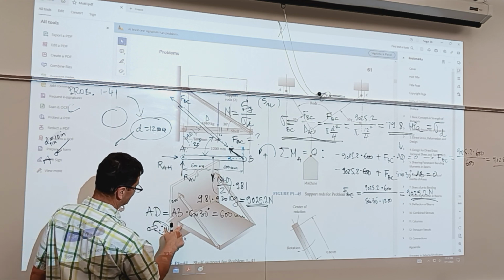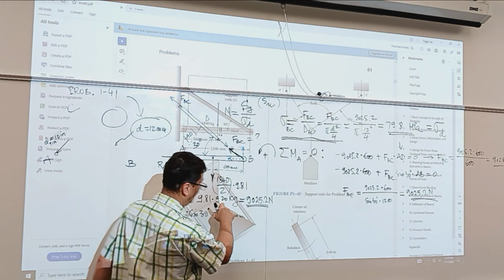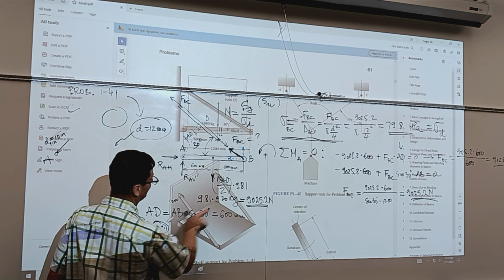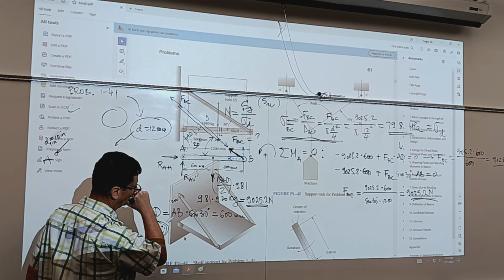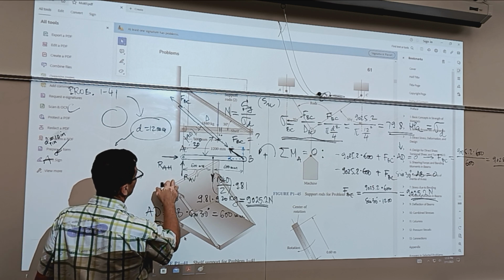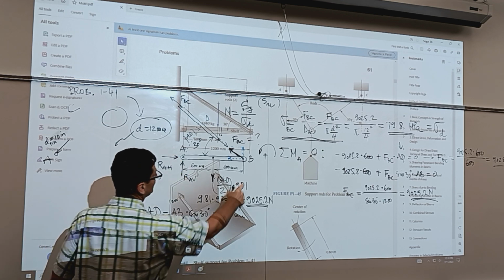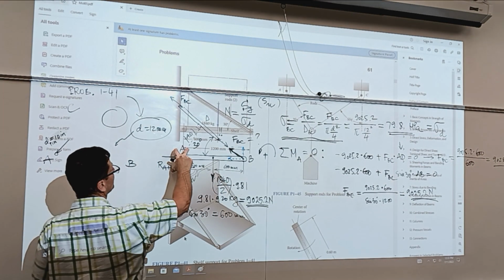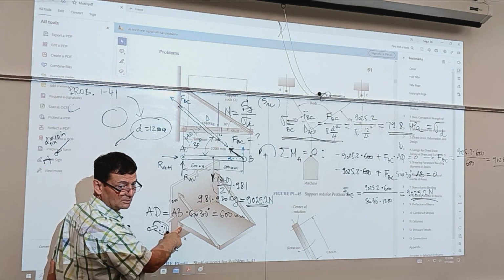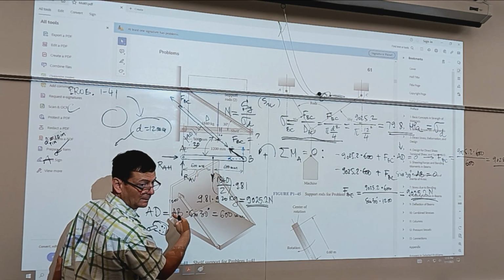In any case, this is single shear here, right? And it's single shear here. If we work with the full pin, say it's in double shear, we need to what? We need to take this, and don't forget, this is just for one side. We need to double these going back to the full load, and then we divide it by 2 again. So we work with what we have and assume the pin in single shear. Does it make sense? Again, we analyze just 1/2.